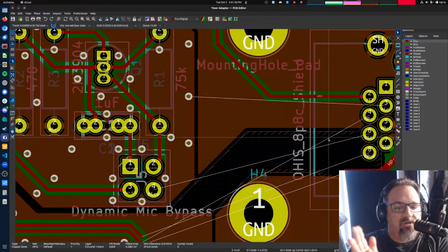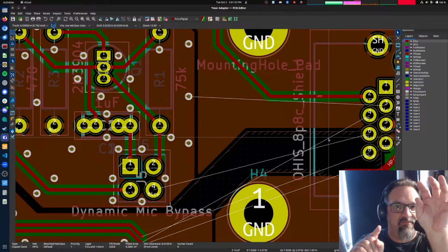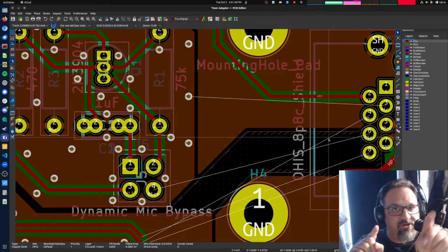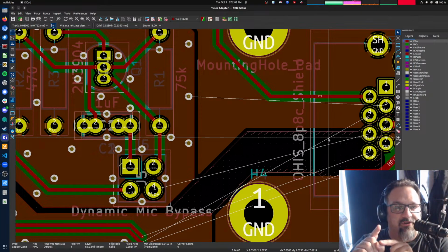When you have a little bit of impedance in series with your ground, you're sending current out the transmission line to whatever is on the other side, whether it's a microphone or a headphone or a speaker or an LED. That return current has to come back some way, right? And it comes back through your ground.